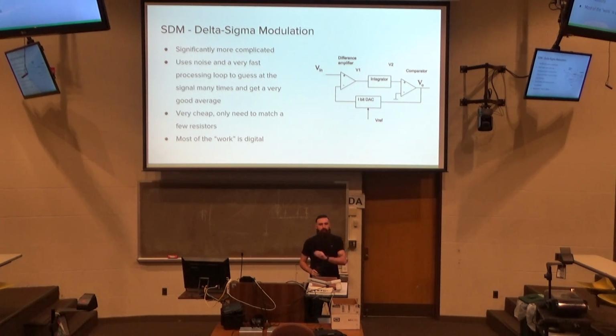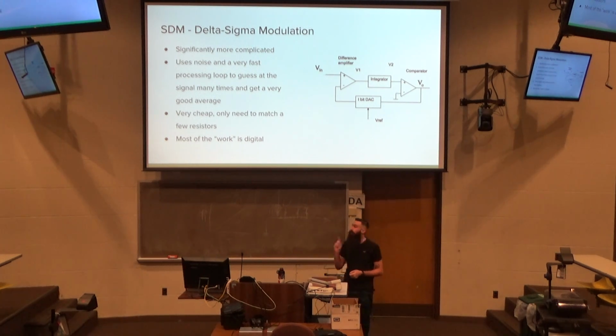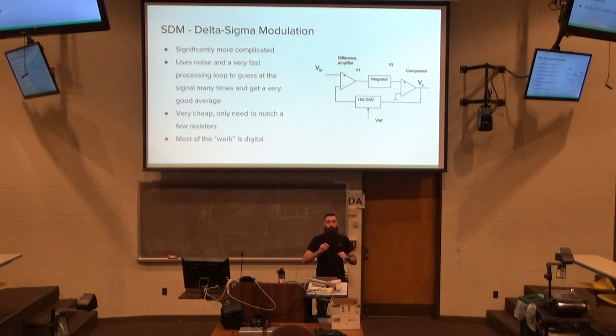This is definitely not as in-depth, and we're going to get more in-depth as we go on. We're going to talk about showing how the waves actually work, and how they're actually converted and amplified. I have some more pictures that will make more sense, but basically, to do this you only need one bit, because you're using the pulse width modulation that we saw earlier to create an approximation for the wave. Then at the end, you take that pulse width and run it through a simple filter that we'll look at, and it will make an analog wave really perfectly. It's super weird. But we'll look at this more in a second.